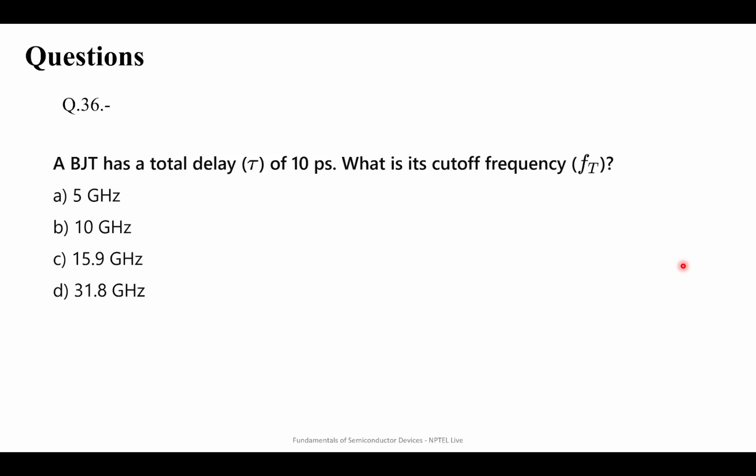So if your emitter material is metal, your depletion will lead to a higher depletion width. So it will lead to narrowing in your base because it's a Schottky junction, and so your base width will reduce. So your beta should increase. I am not sure about that, but I think your beta should increase if your emitter is a metal. But I am not sure about that.